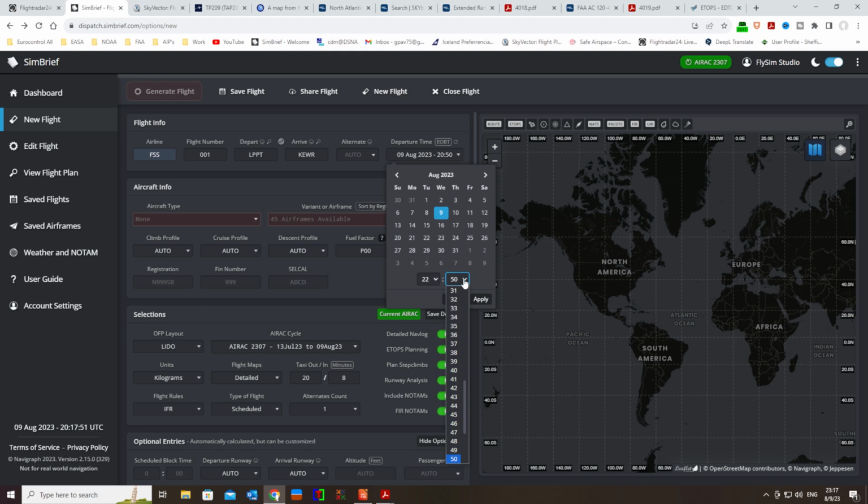Usually when we do flight plans including ETOPS, we are flight planning them 3 hours before departure at the minimum. The minimum time is 3 hours. Below that, it's considered to be really critical. However, we plan even earlier, and we are cross-checking the winds 3 hours before.